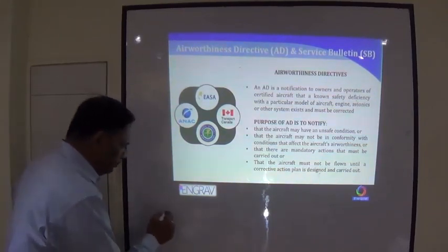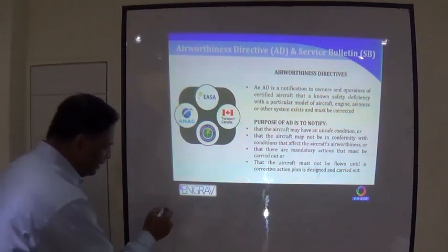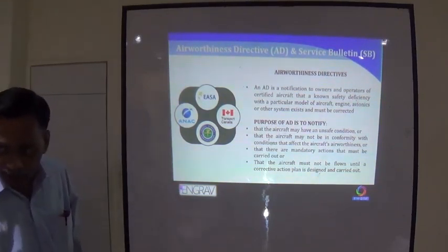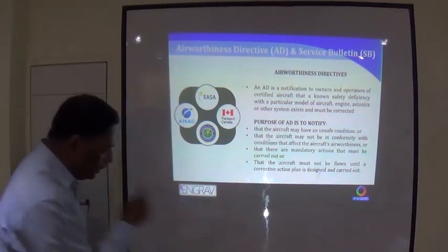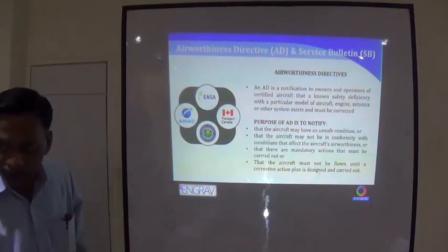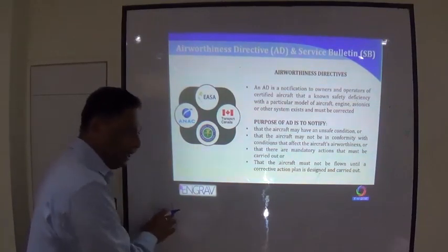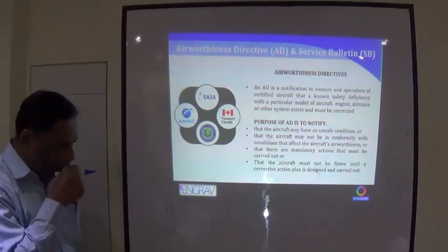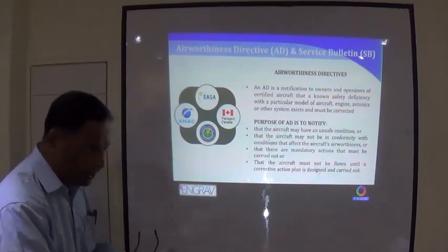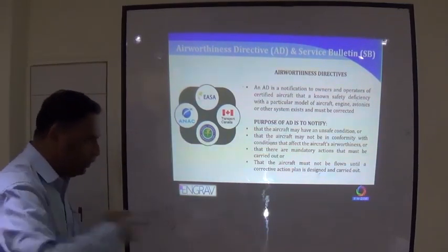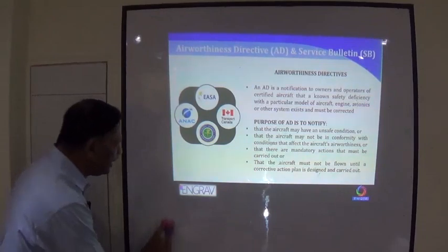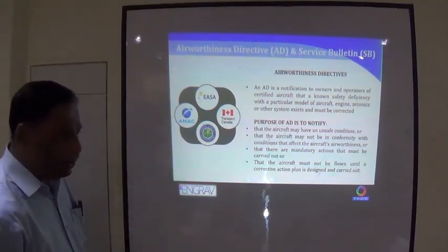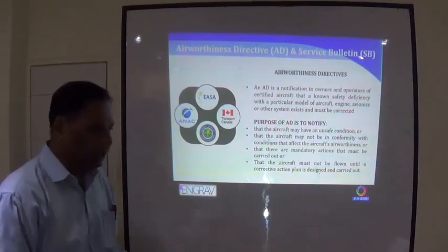Generally, a pilot cannot take off unless he accepts the aircraft. The CRS is issued by the engineering and the pilot accepts it. Second, he has to have the load and trim sheet. He has to accept that load and trim sheet also, which will give a full understanding to the pilot of what is the total weight on the aircraft, where is the CG currently, and whether the CG is exceeding the forward limit and aft limit during the sortie. There are people trained to calculate this, and software also can calculate this. In our system we are calculating it.